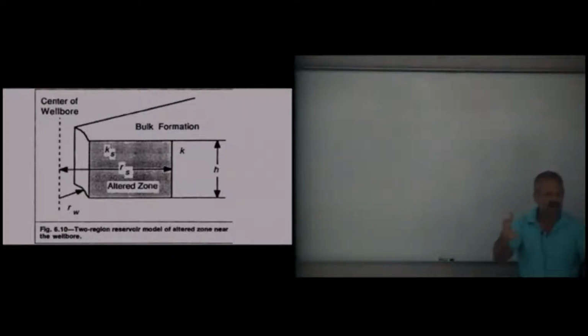This is going excellent, right. We drill overbalanced. The weight of our mud is greater than the formation pressure. If we run across a porous formation, what's going to happen to that mud? It's going to leak into the formation, and that's what's depicted in this picture in the shaded area.